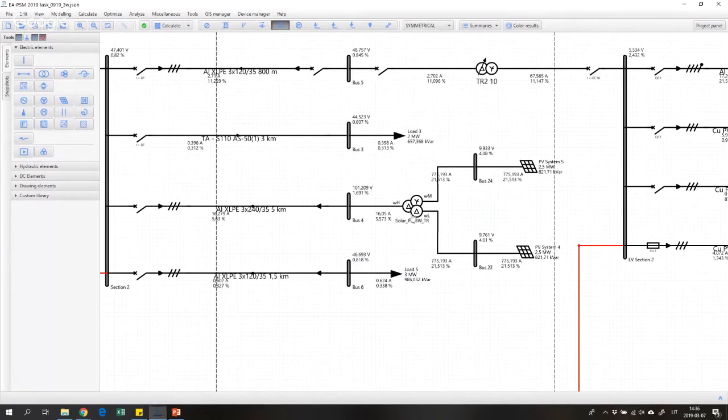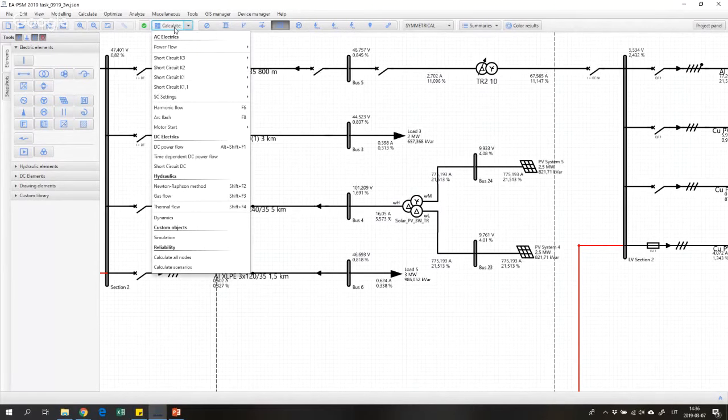So they use this kind of equipment to mitigate harmonics. In Europe, we more commonly use filters for harmonics. So again, it's possible to also evaluate filters with this kind of software. So what we look at now are the main features that are required by a distribution system operator when we are evaluating solar power plant installations.